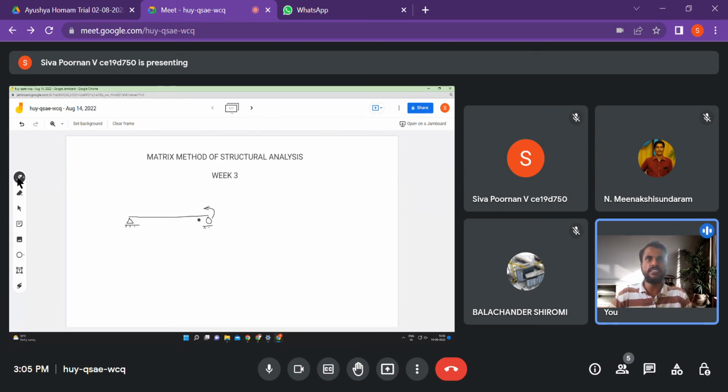Then we have discussed in the previous class how to solve for the rotations and displacements at the ends, right? Now let's say that there is not a point moment, but there is a distributed moment, okay? So something like this. So it is similar to a distributed load. Uniformly distributed moment is what I have in the structure. Can you find out what is the displacement and rotation along the span of the beam? Bending moment profile, shear force profile, deflection profile of the beam.